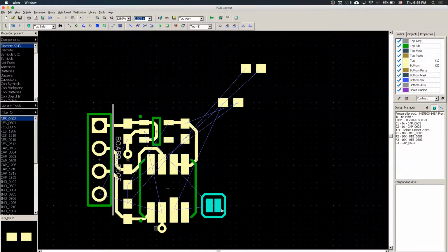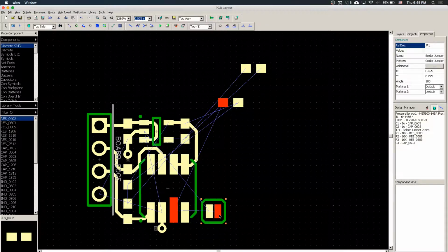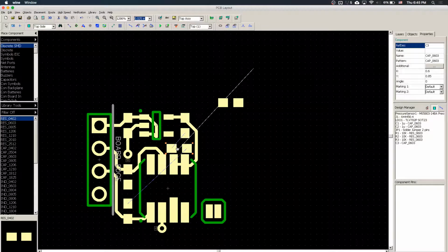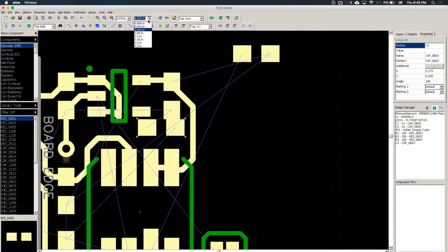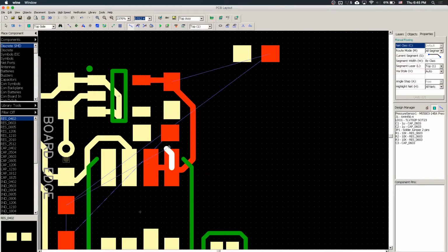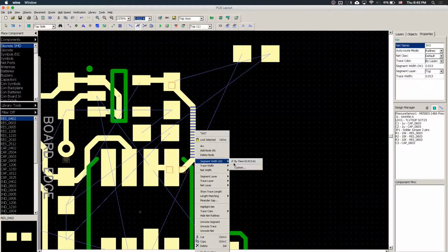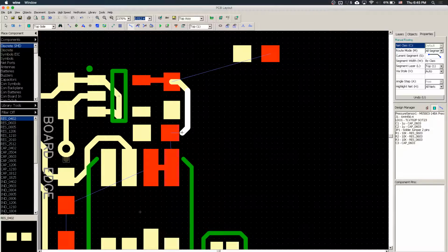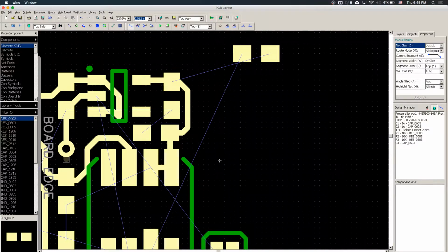And this is our address select, and we're going to select the address based on that. But first thing first, we're going to move our capacitor up a little bit and put our bypass capacitor next to the VCC of the chip. So this is a resistor, and this is our bypass capacitor. And as you can see that it won't fit well, so I'm going to reduce the grid by a little bit as well, and try to connect it like such. So for bypass capacitor, it will be better for you to go through the capacitor before you go to the pin. So I'm going to try to do that for the capacitor and connect it like that.